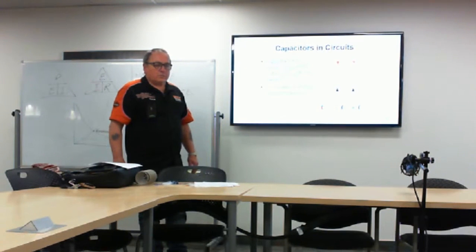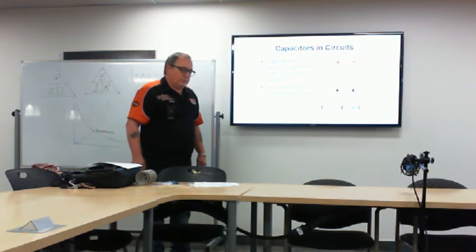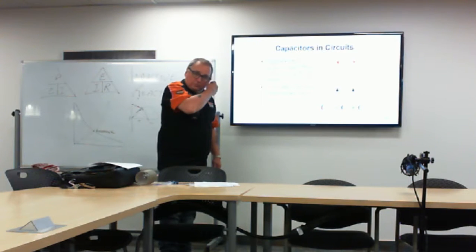But when you switch to the 80-meter band, because it's resonant on that frequency, it'll pass that frequency, and all of a sudden your antenna is working on 80 meters. So you have one antenna with these traps on it, those parallel tuned circuits, that becomes a multi-band antenna.